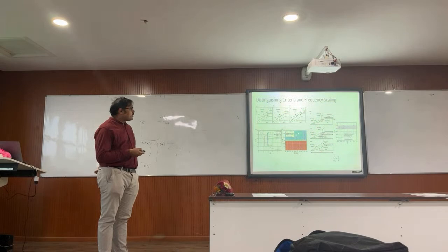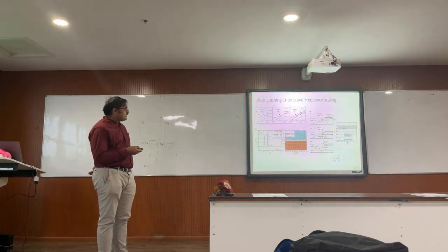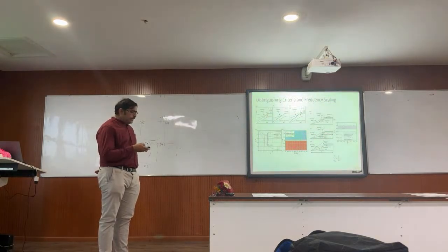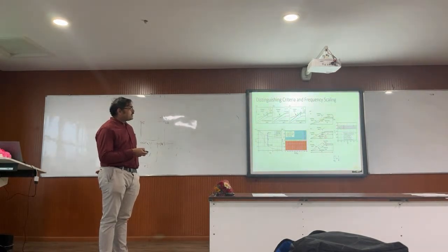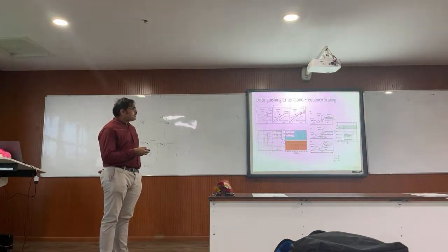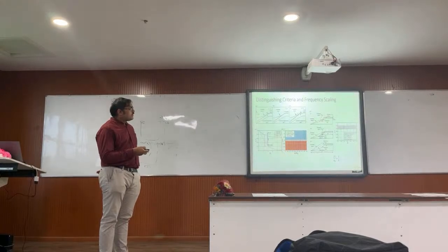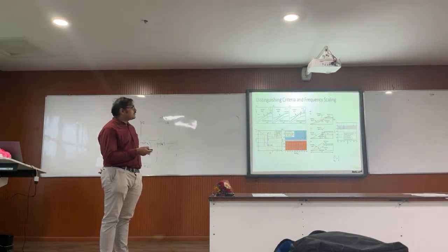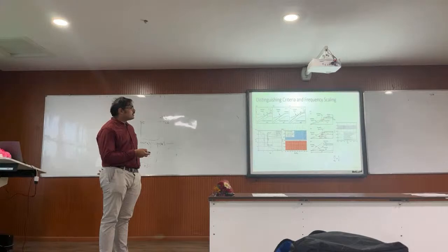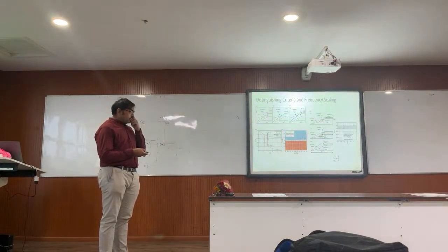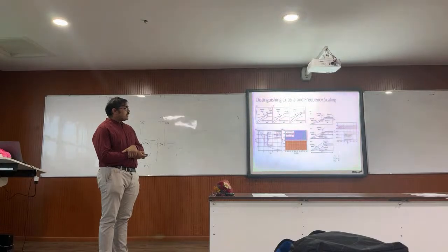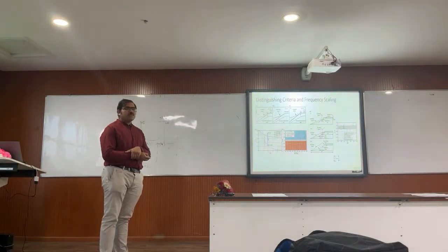And we have not only our studies, we have used several other studies and shown that this actually forms the boundary. And also, what kind of scaling does this give? So this mainly is decided by the extent of the subsonic region in this particular flow. In all these flows, we find that there is some subsonic flow. It may be small. If you have a shear layer cutoff here, the subsonic flow is very small. While if it is subsonic all through, then you have a very large length of subsonic flow. So the length of subsonic flow actually decides the scaling. And if you scale the frequencies according to the length of subsonic flow, then we find it takes the value 1 by 4. So it becomes a constant.